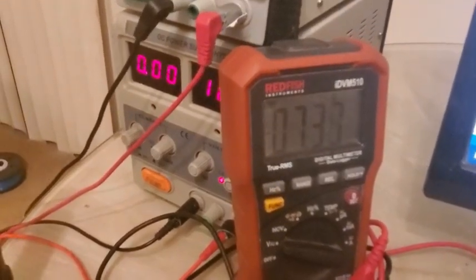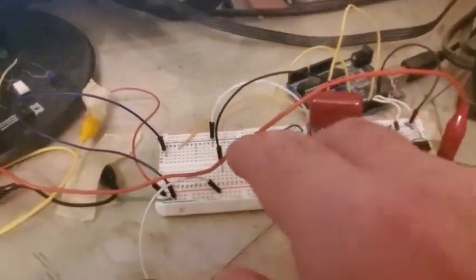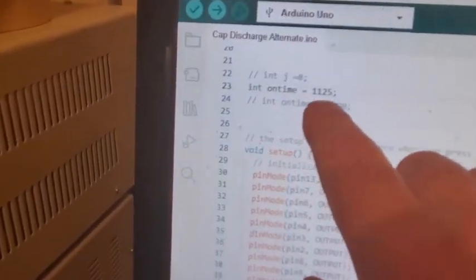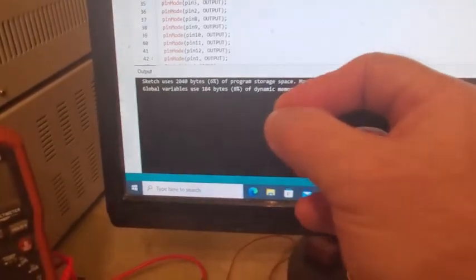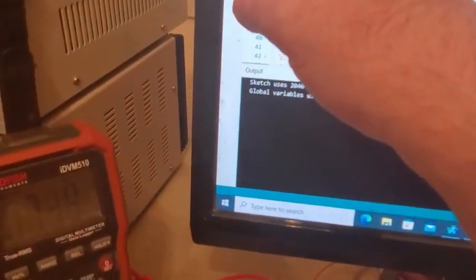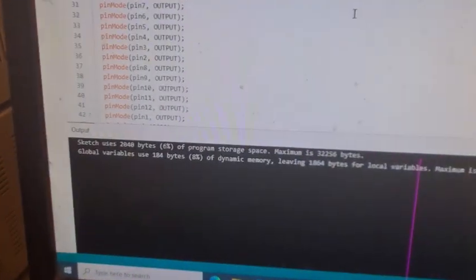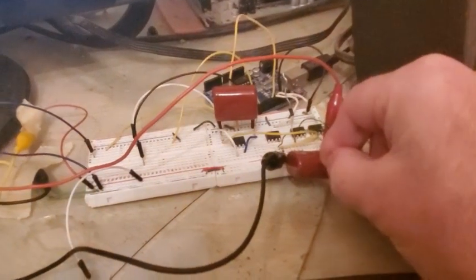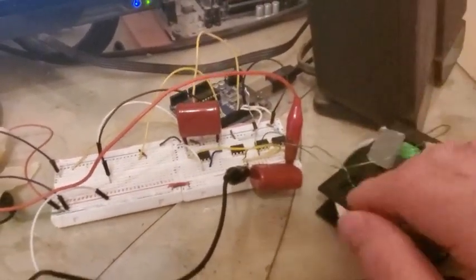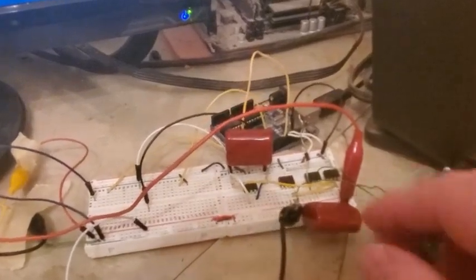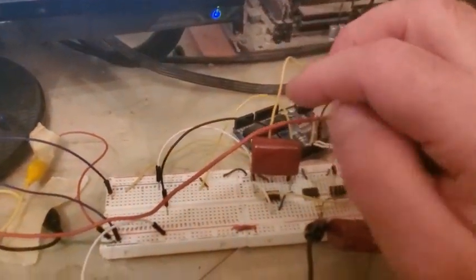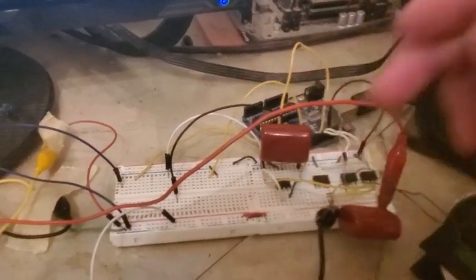So now I'm going to do something new. This will be new for me. What we're going to do is reconnect this diode and shoot it out to here. We'll measure what's going on in this cap. So if we divide this in half, and now we disconnect it at whatever that'll be, 661 or 2 microseconds, that will be the 0 point. And then that's where the field is strongest. Then the field will collapse. And the same voltage should show up, that negative 7.4 or whatever, in this cap with one pulse. And if it doesn't, I would say that's losses over the diode.